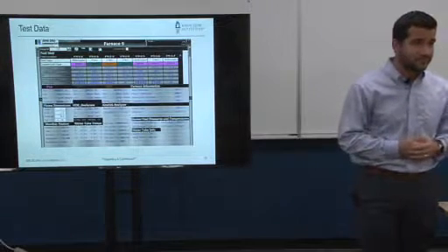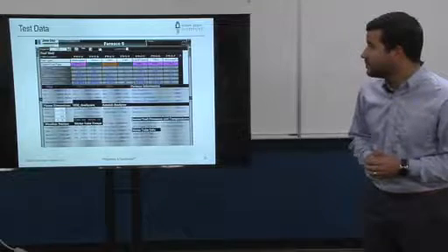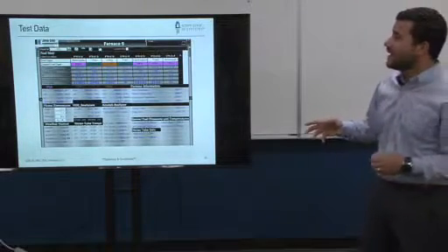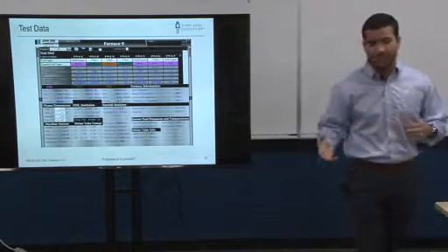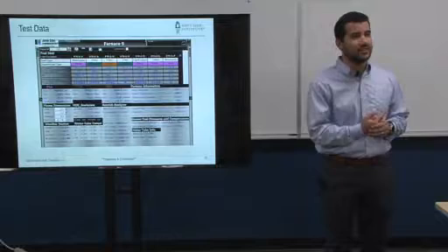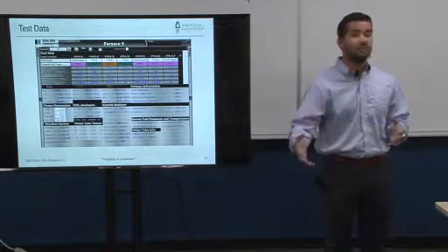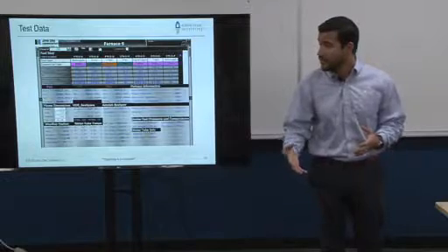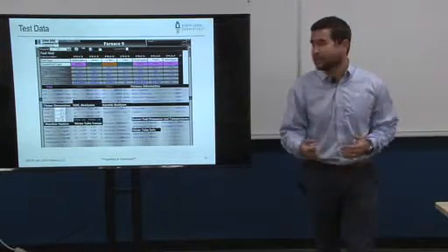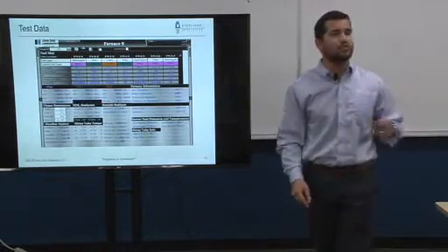So what is custom fuel type? How many fuel types over here? Fuel type, custom fuel type. Okay, so in this particular case, typically a burner will have only one fuel connection. But there are some applications when there is a byproduct that gets injected in the burner. Okay? So in this case, that's the pink you see, it says PSA. That's pressure swing adsorption.